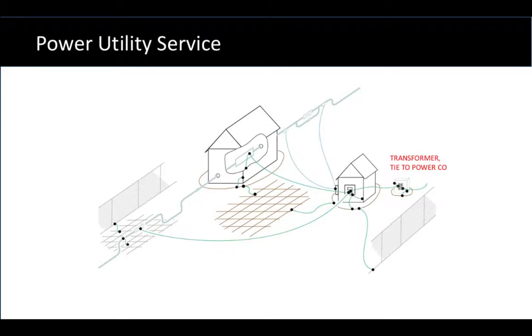Let's say that this station actually was a compressor station or a large pump facility. It could be that there's much more equipment and piping than I've shown right here, and there's many points of possible contact of the pipeline to the grounding system where the CP could be shorted out. Those sites can be so complex that you can't even sort out all of those bonds, because if you missed even one, it's like you had done nothing at all. Then you might be able to see how separation from the power company becomes important. Because by default, power company grounding systems connect to user grounding systems for safety. And it's that tie that we have to address.